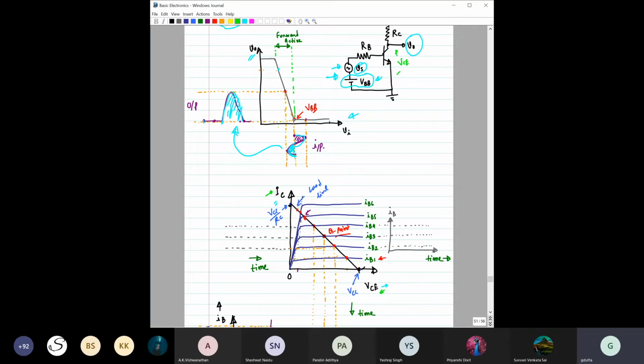Right? And what is IC? IC is the current which is simply flowing through this, right? So we know that this IC versus VCE characteristic would be like this, right? And here we have also seen how to draw this load line, and say the Q point we have fixed to this point, right? So we have set these other parameters such that the Q point is almost at the middle. Now again consider this circuit.